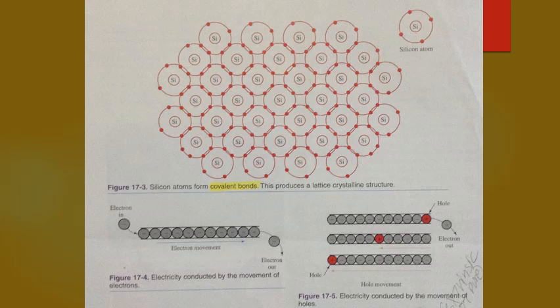The hole is strongly attracted to another electron. The hole is positive. The next electron fills up the hole and leaves a positive hole in its place. Each positive hole is filled in turn by the next electron. When a vacant hole appears at the other end of the conductor, this chain reaction is conduction of electricity by holes. The study of semiconductors is concerned with conduction by electrons and by holes.